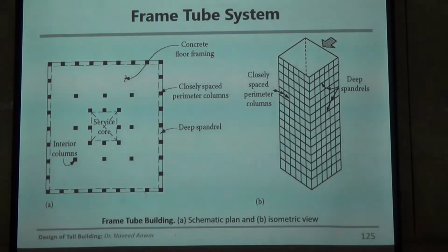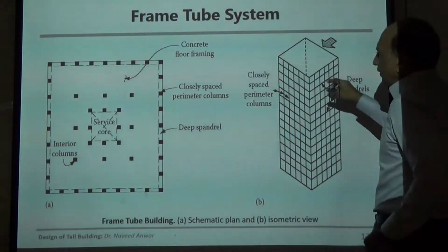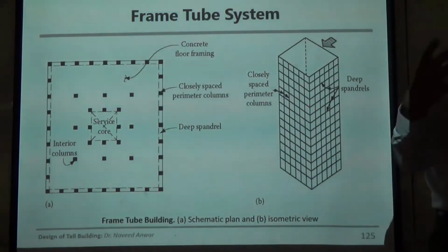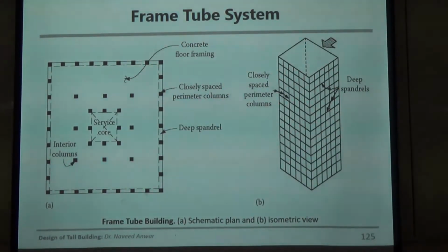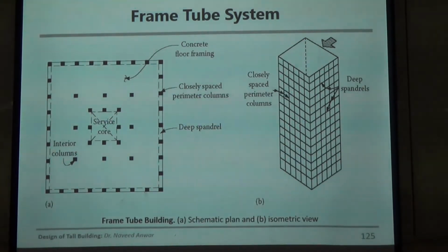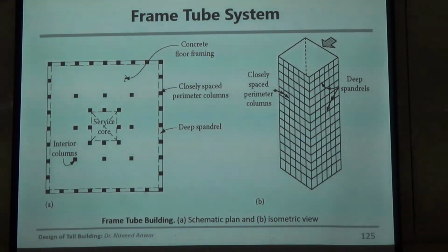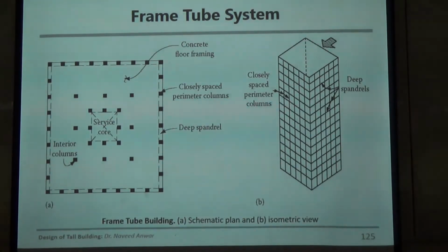that wouldn't happen. Because that tubular system was designed in such a way that the core and tube were not connected at all. The outer tube was independent steel columns and nothing in between, and the floor was simply resting on the core and the outer wall. No interaction between them. The floor was very thin and not rigidly connected; it was just pin connected. Core and outer tube were just pin connected. So when one floor collapsed, everything went down.